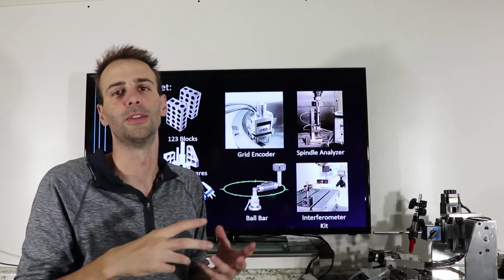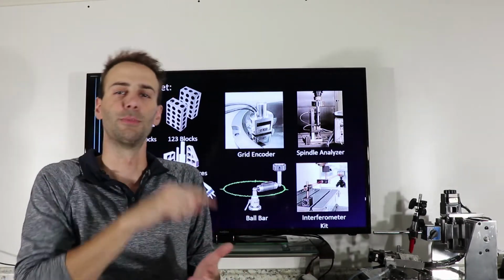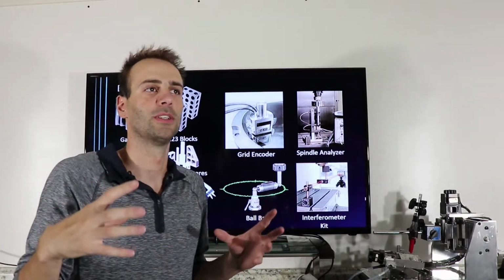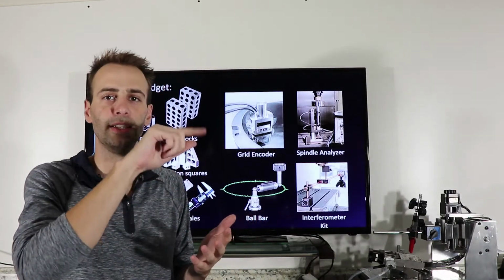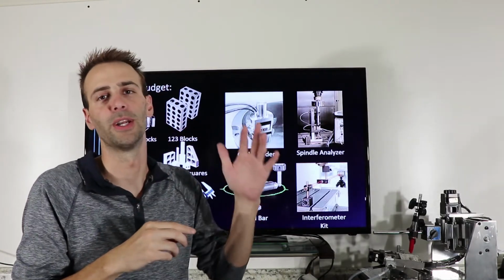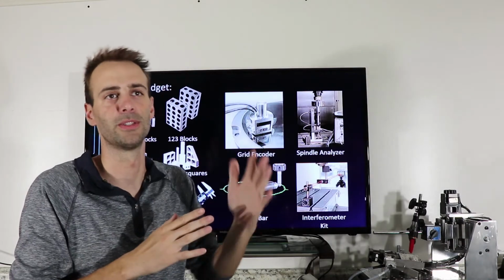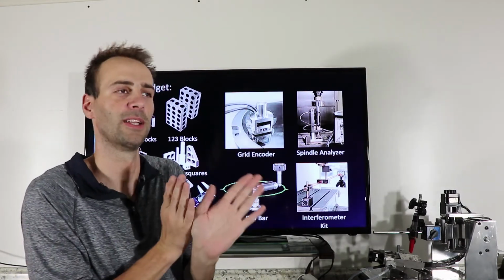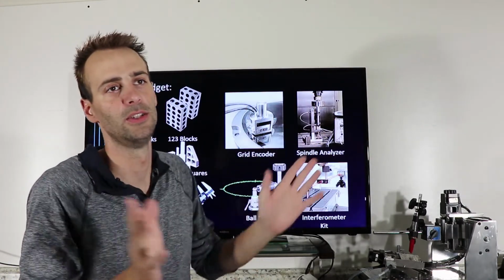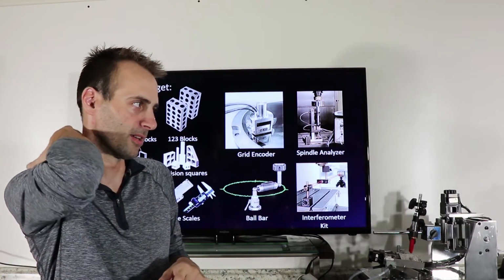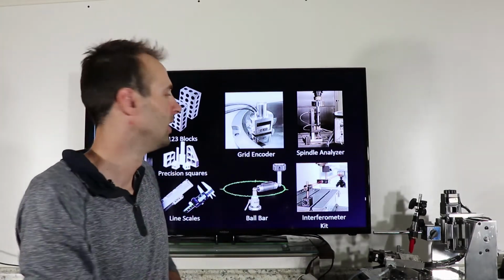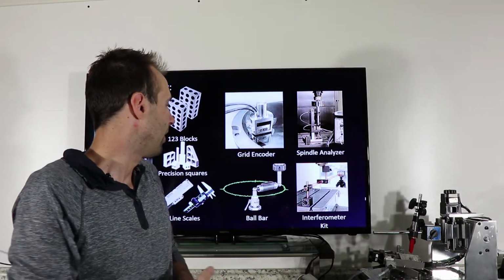Well, first of all, is my circle round? Is it elliptical? Is it jagged in certain spots where I might want to slow down the machine when I'm running at a 45-degree angle, or say my X and Y have to do coordinated motion, right? Like the servo error kind of compounds. So you can kind of map out machines.